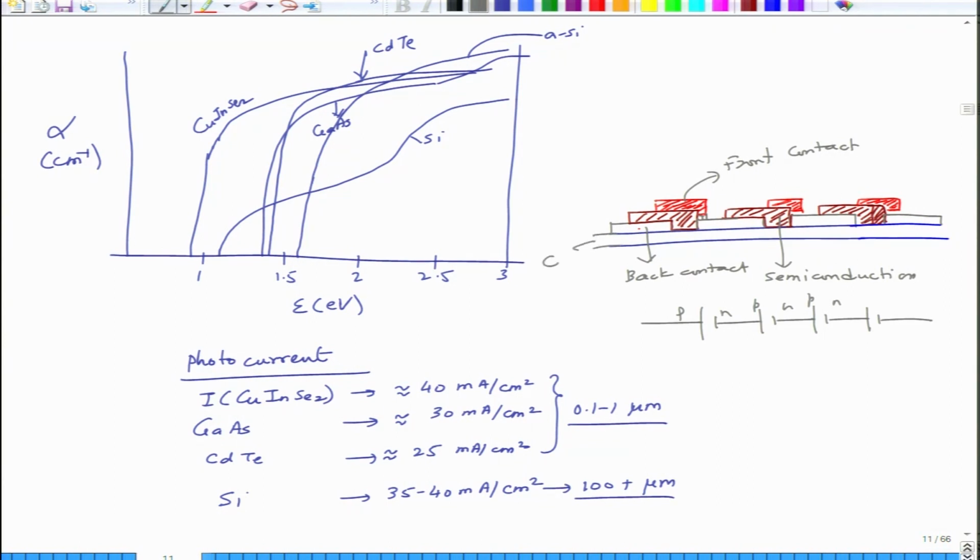This glass panel is cheap. Okay. That is not as expensive as the material is. You are putting only a micron of material, which is 100 times lower than the amount that you need to use in silicon, and then use a front metal contact, which can be put by a process like evaporation or something like that. So, the advantage here is that you are able to make a junction, and from the front the light will come. Light will also come from here.